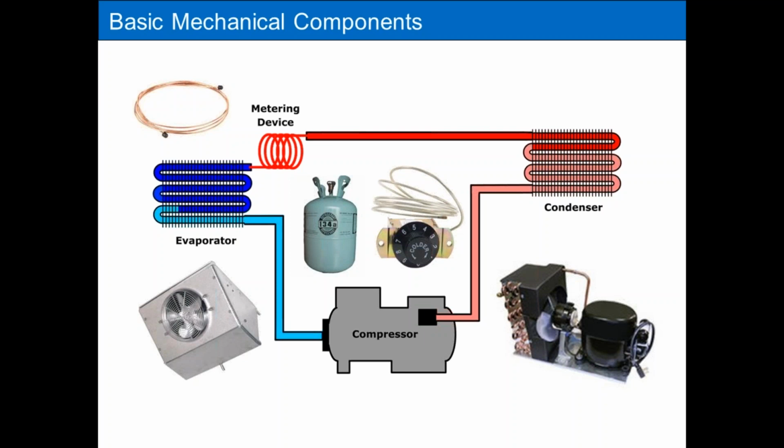And then the refrigerant. For the most part, on medium temperature systems of this nature, you're going to see a lot of R134A systems. If you work on a really old system, an original R12 system, you may see some blends out there that have been used to replace the 12 that was originally there, and you may even come across an R12 system that is still in existence. But it's been a while since 12 has been obsoleted, so most of the time it's going to be 134A that you'll be working on.